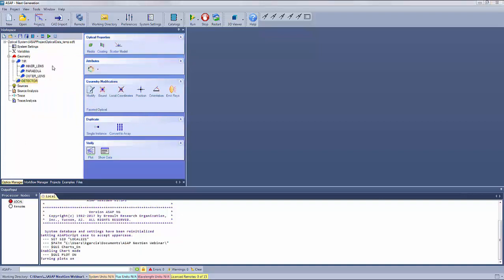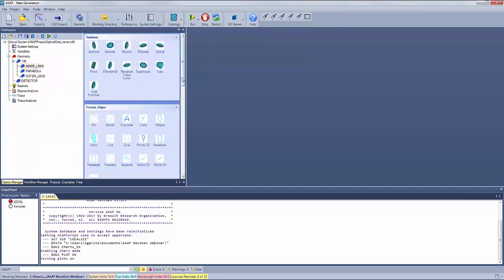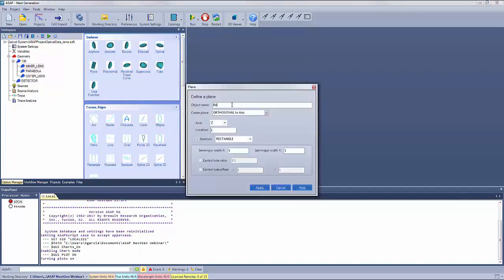Now we'll begin defining the actual geometry for these different components. Let's start with the inner lens. We're going to create a geometry component here, which is going to be the base. We'll create that out of a planar element. We'll call that base. We'll come down here and set its location at 0. It will have an elliptical aperture. And here we will use some of our variables which we previously defined. Base semi-diameter, and it'll have a central hole.